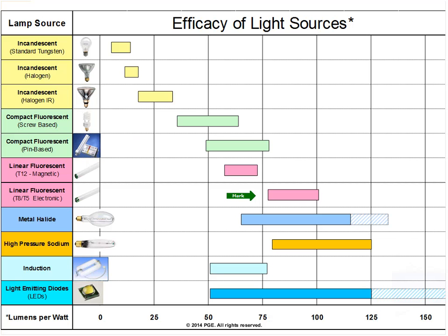One thing you notice on this chart is that both metal halide and LED, especially LED, have room for improvement, while the other sources have pretty much peaked as far as how good they're going to get. Very little room for improvement. With LED, they're saying that we might even see lumens per watt of 250 lumens per watt someday. But keep in mind, efficacy is just the starting point of our light journey.